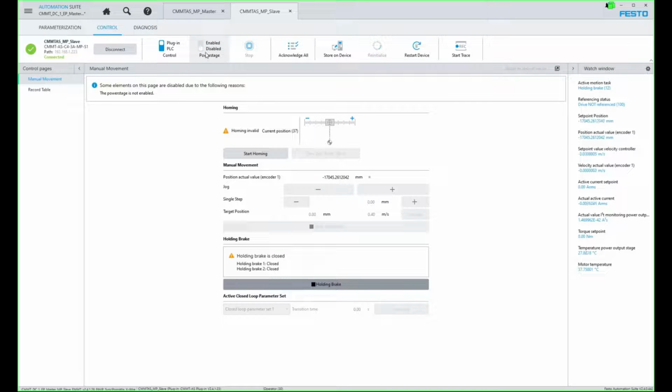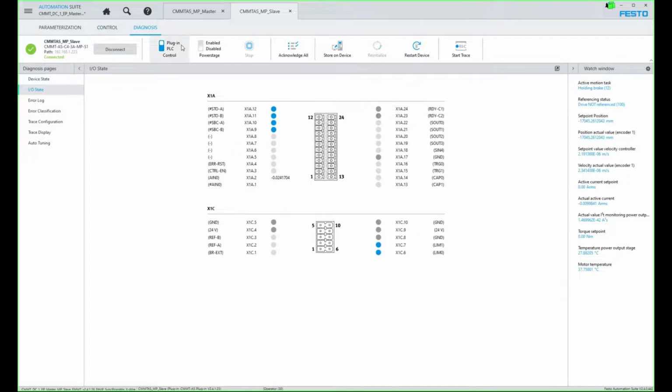Okay, so I'm going to go to the control here. I'm going to, well, I don't have to do anything. I just need to basically try to enable it because there's no physical control enable. And because there's a fault, I've lost the control enable over here on the master. I don't see why the ready C1, C2 are not being updated here, but that's just the way it is. I don't know if that's a flaw with the software, but basically the slave controller needs to have no faults before the master can be enabled, unless the bypass is active.